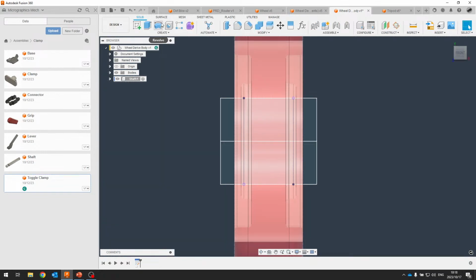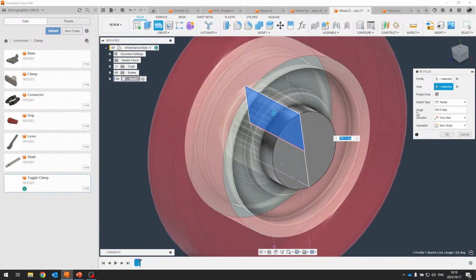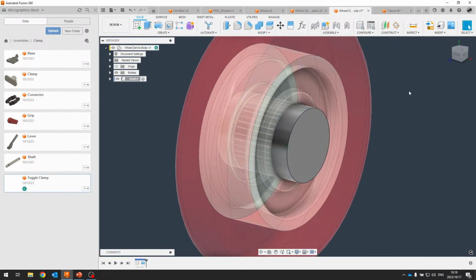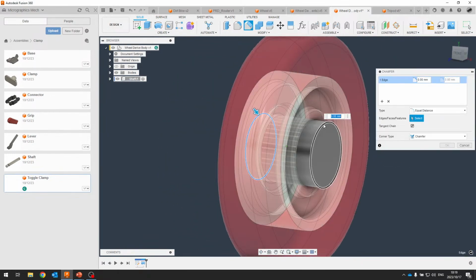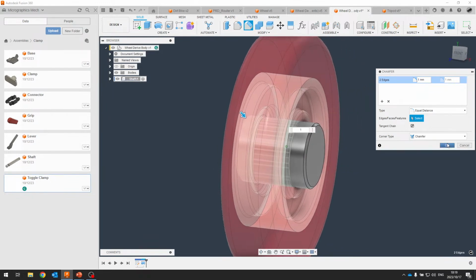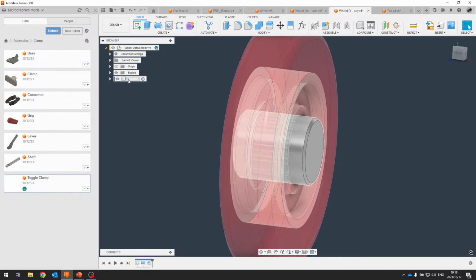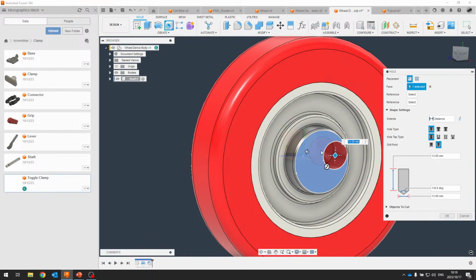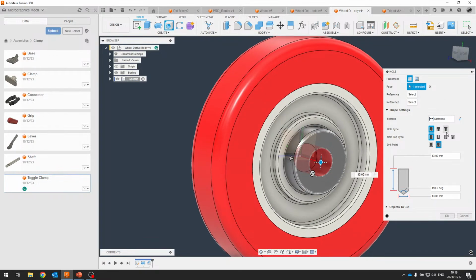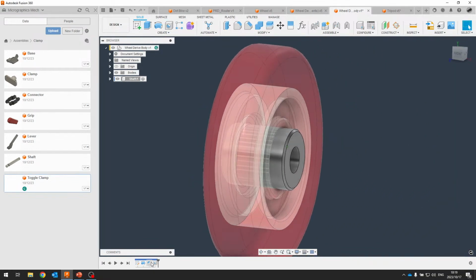So what I'm going to do here is then just revolve half of that. Probably would have been easier ways to do it, but just going ahead there and putting in a design. I'm just going to add some more details, so just a little chamfer on either side. And we can see at the bottom here, we've got the timeline for this component. So the shaft is a sketch, a revolve, and the chamfer. I'm going to add a hole through here just for the sake of adding another feature. Let's do a through hole. And we then have that feature as well.